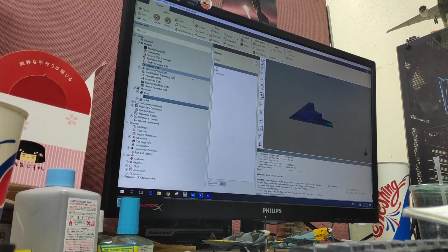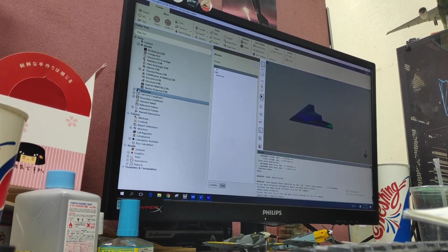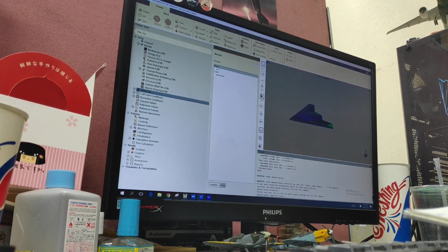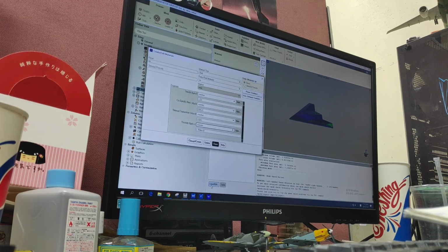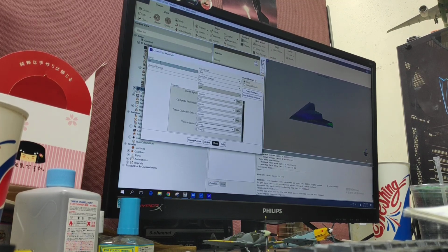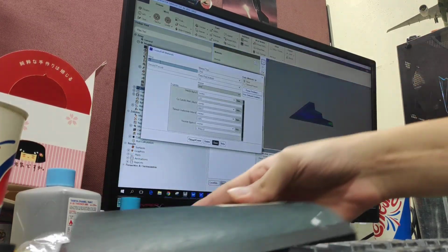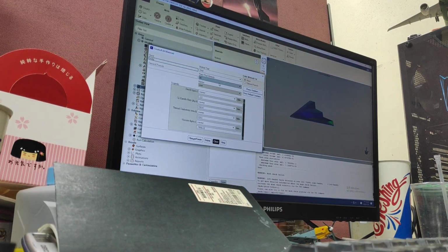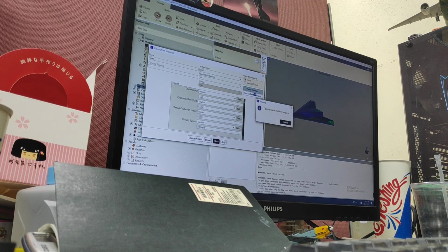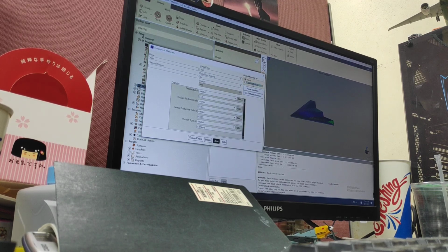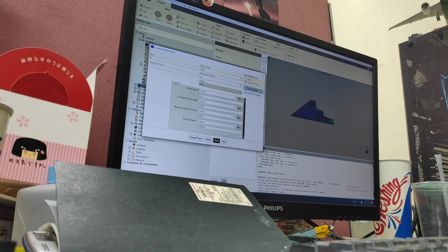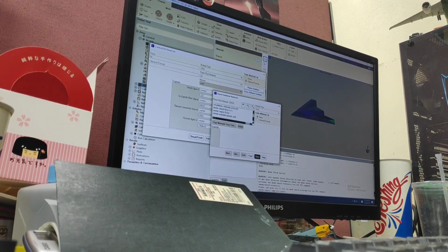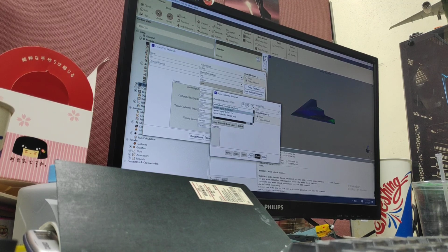Okay, if you still want to use the water, right? So you can here go to fluid, and here's create and edit, and you can type the name water and choose okay, chemical, fluid data, and then choose the water liquid.